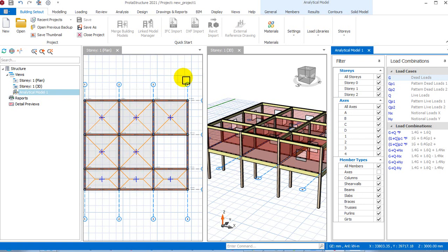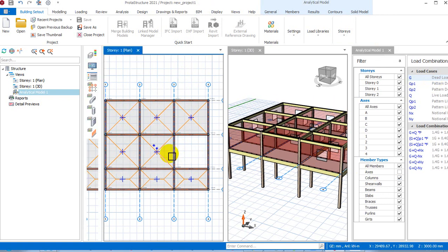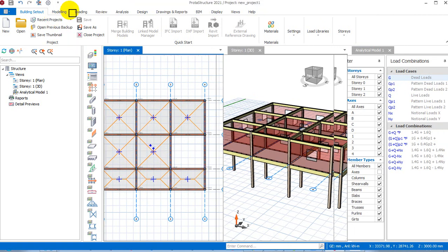There are three different things you can do to make your slab safe: change the depth of the slab, the size of the reinforcement, or the spacing of the reinforcement. That's the essence of slab strip. Okay.